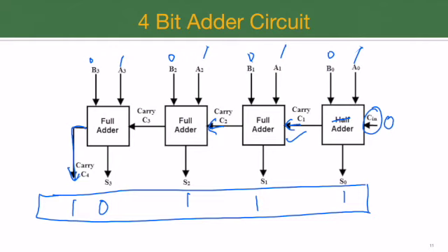Okay, so this is a 4-bit adder circuit. If we want to produce an 8-bit adder circuit, we just need to add 8 full adder circuits in series with the carry from one level being added to the next level, and that will produce the result of addition of 8 bits. Similarly, 32-bit, 64-bit operations can be created. Now,